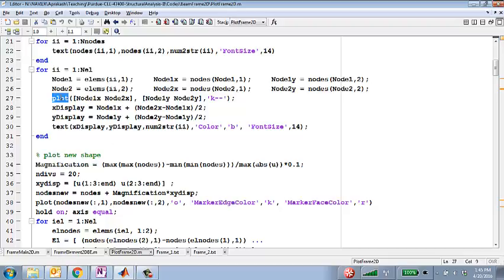How do you plot the new or the deformed shape? You take the displacements, you add it to the old coordinates, you get the new coordinates of each of those nodes and connect them not with straight lines, but with functions that actually depict these 4 shapes.